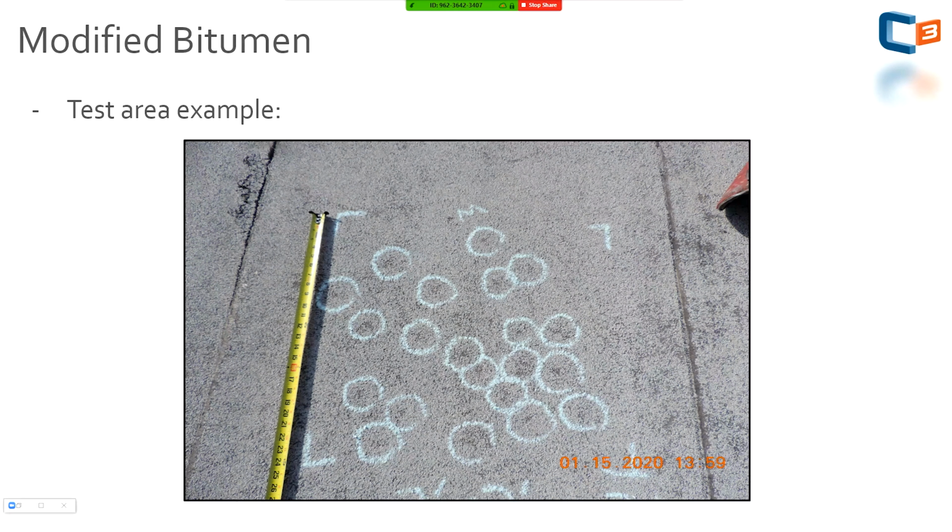So on these, generally, it's kind of similar to shingles in this case, except for the size of the test area. At C3 Gear, we generally don't do 10 by 10s on commercial roof systems. The reason being, on a sloped roof, you imagine you have shingles installed, right? They're small. If there's a repair method prescribed, you can follow that. You can replace maybe one or two shingles in a test square, potentially. Obviously, there's a lot of considerations there to think about.